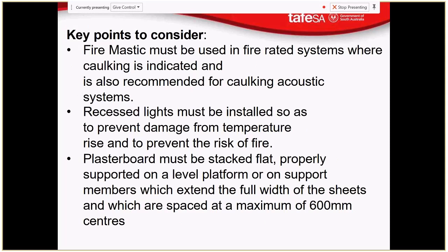Plasterboard must be stacked flat, properly supported on a level platform or on support members which extend the full width of the sheets, which are spaced at a maximum of 600mm centres.